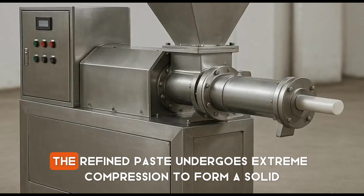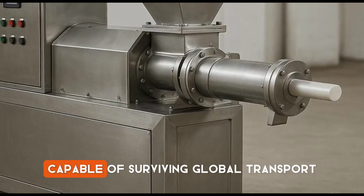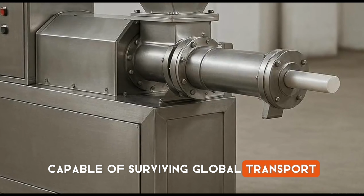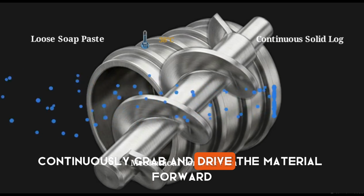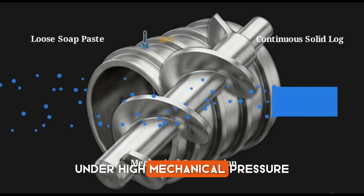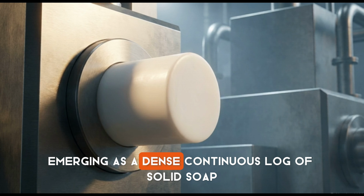Inside this barrel, the refined paste undergoes extreme compression to form a solid capable of surviving global transport. Massive internal steel augers continuously grab and drive the material forward under high mechanical pressure. The paste hits a specifically shaped die and is forced outward, emerging as a dense, continuous log of solid soap.